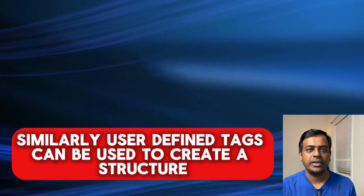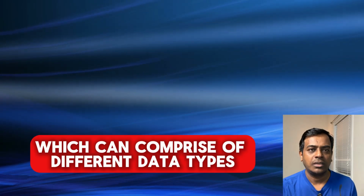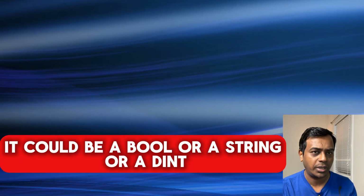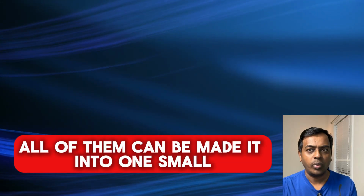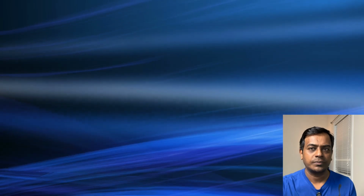Similarly, user defined tags can be used to create a structure which can comprise different data types. It could be a bool or a string or a DINT. All of them can be made into one small custom data structure that we can reuse.